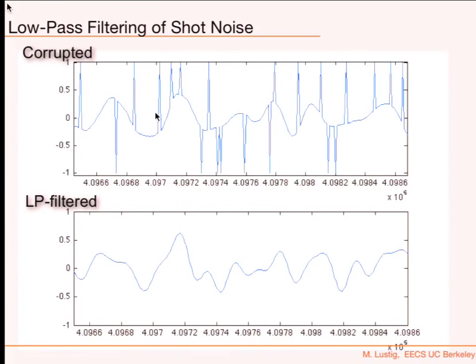When we filter this using this linear operation, those spikes create huge bias on that estimation, right? Because we're doing a linear operation. What is a filter? It's a weighted sum of nearby samples, right? The spikes are just always going to bias this. And so we get a distorted signal that doesn't look like the original one.